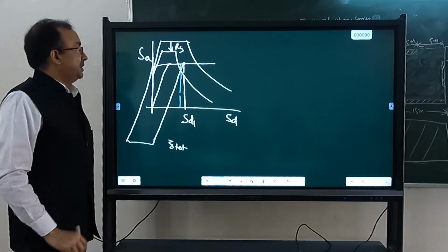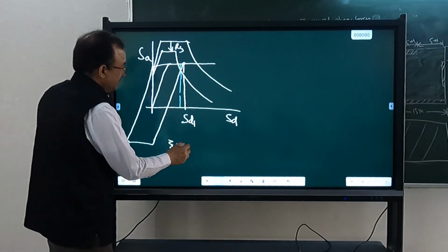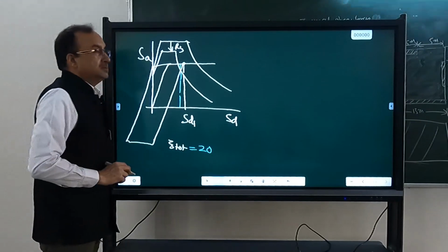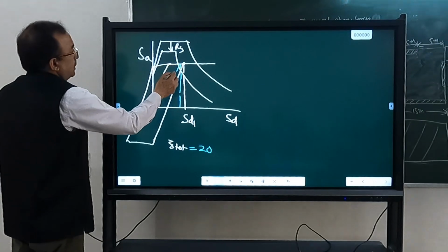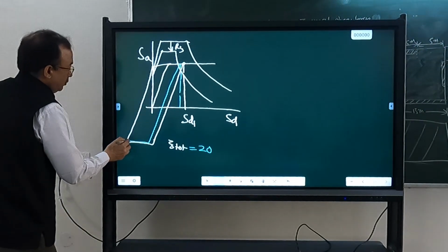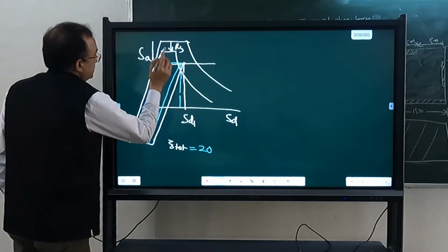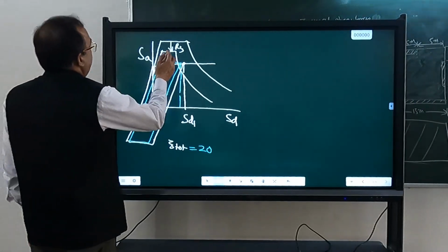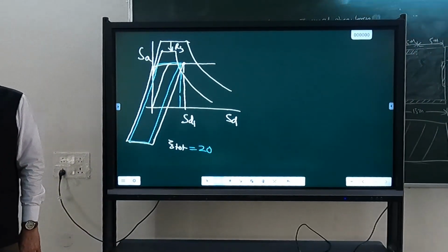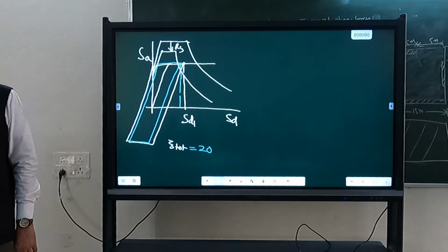Let us say earlier this was 20%. If I have reduced the displacement here, what will happen to the equivalent damping? Is it going to reduce or increase? What will happen to the area of the hysteretic loop? The area of the hysteretic loop is going to reduce. And if the area of the hysteretic loop is reducing, what will happen to xi total? That will also reduce. And if xi total is reducing, what will happen to R xi? It will increase. Less reduction.